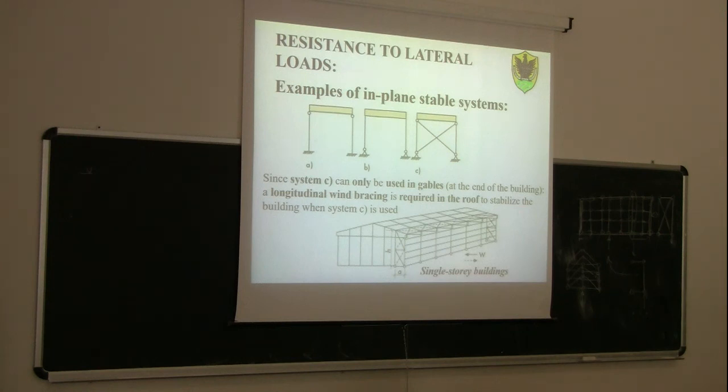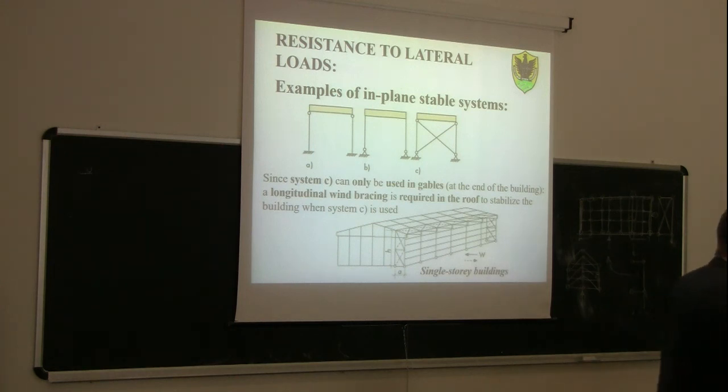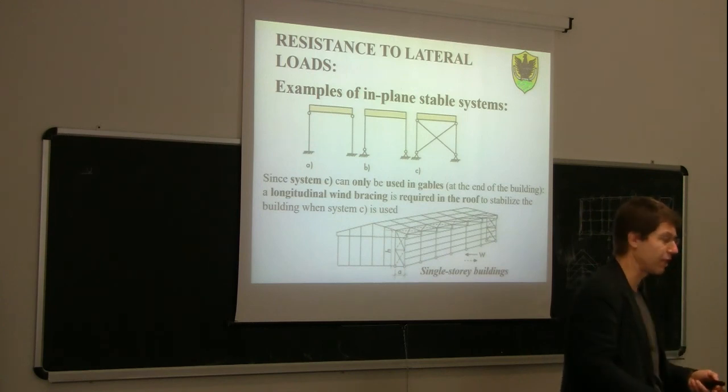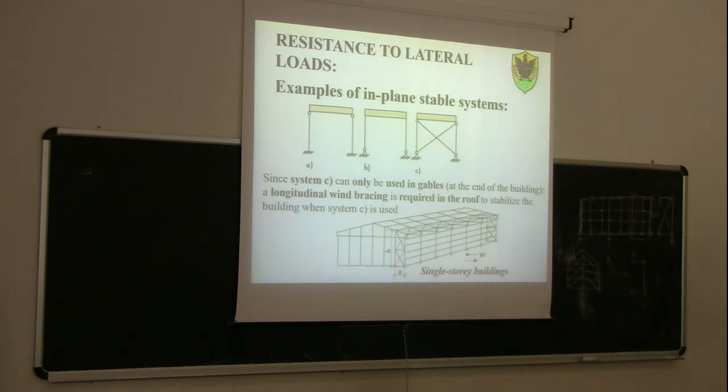How can I make this system stable? Well, the criterion is what we already learned, what we already discussed in reinforced concrete. We need to make the floor in-plane rigid. The problem here is that the floor is not in-plane rigid. So what I need to do is make the floor in-plane rigid. How can I make this floor in-plane rigid? Yes. Either I need to use very stiff panels, in-plane stiff, could be plywood, but I'm not sure if I use these sandwich panels, unless I nail them all along the whole perimeter, this is not enough.